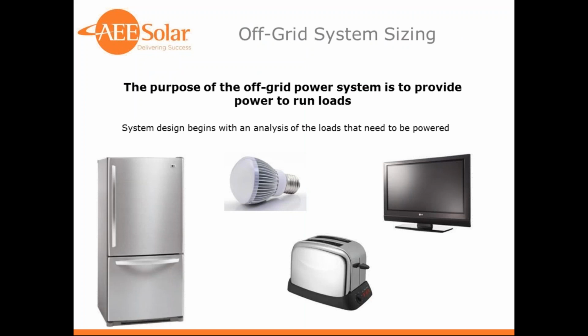So when you're doing off-grid system sizing, you have to remember that the purpose of the system is to provide power to run loads. We're not just producing kilowatt hours of energy here, we're actually producing power to run loads. So the first place to start is to do analysis of the loads. We need to know what loads we need to power in order to properly size the system.